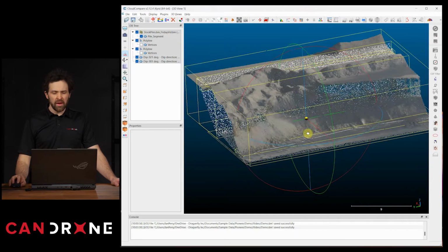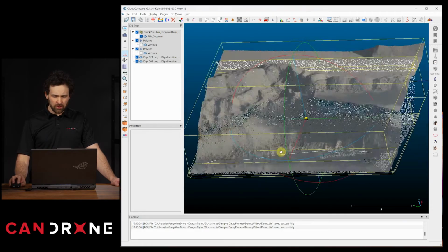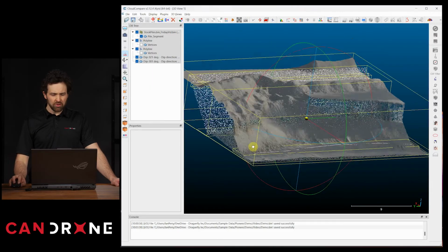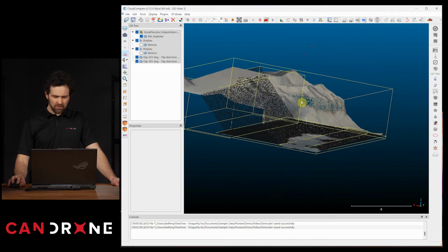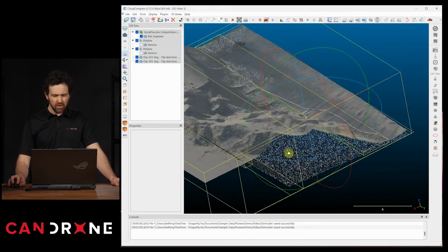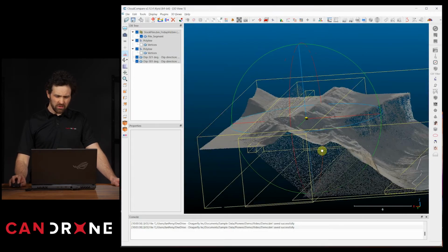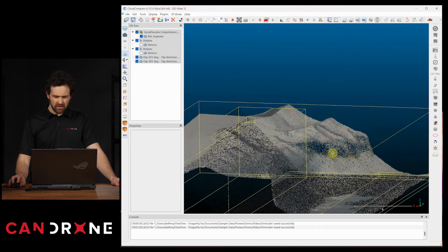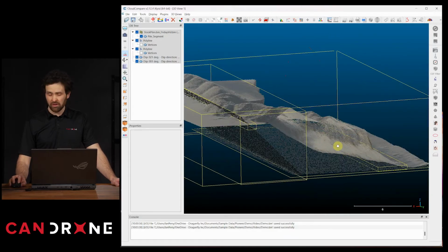So we've come a long way, and what we have here is a nearly enclosed volumetric space. We just have to create a couple of sidewalls. To do that, we're going to use a point picking tool, and that will allow us to actually enclose this volume at each side by clicking on the existing cloud features that we've created with the planes and that we've flown with the L2.